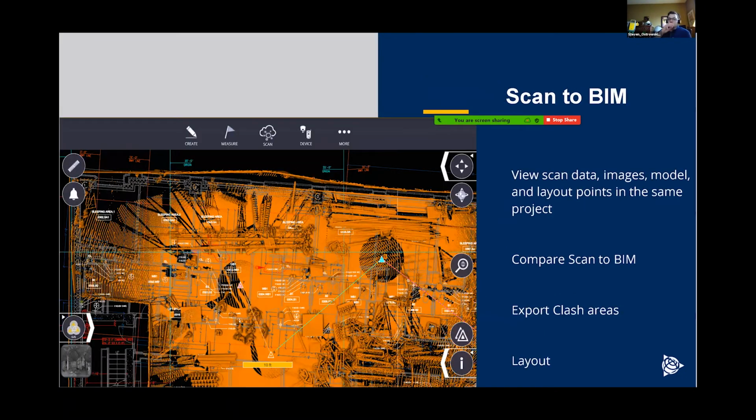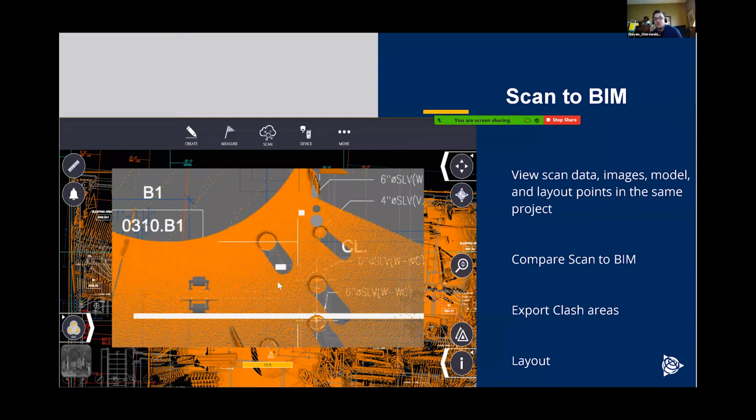Moving into new construction, you can scan and compare back to the model. In this case, this is a 2D DWG drawing where you see where the design sleeves are supposed to go for this plumbing example and how they miss here. You can then update the as-builts, and if you're going through walls or transferring these systems up, you can update the next floor as well. This scan to model comparison took 4 scans, and comparing probably took about 15 minutes out on site. It's very quick and easy to do. And we'll show you a bit of that.